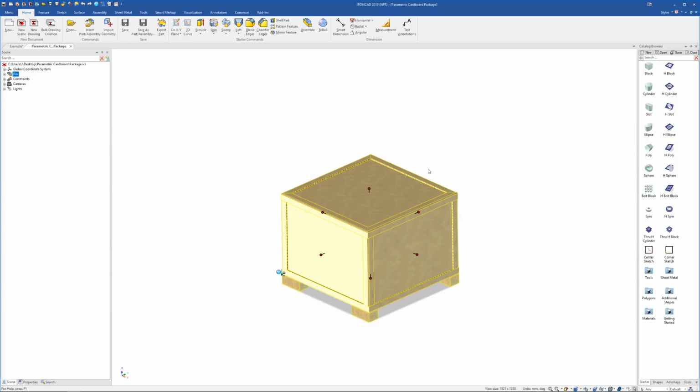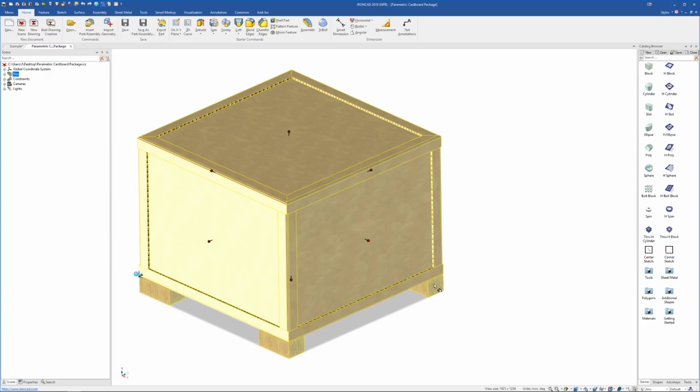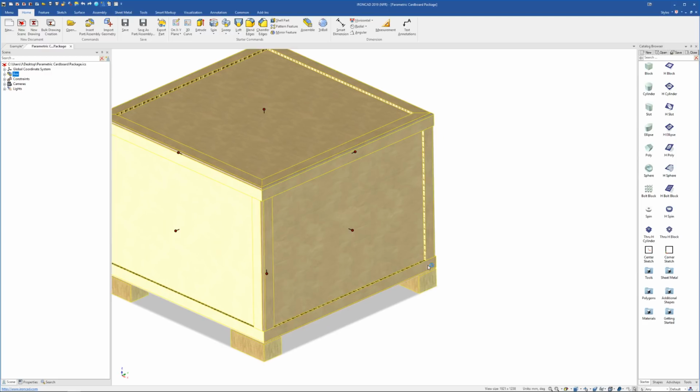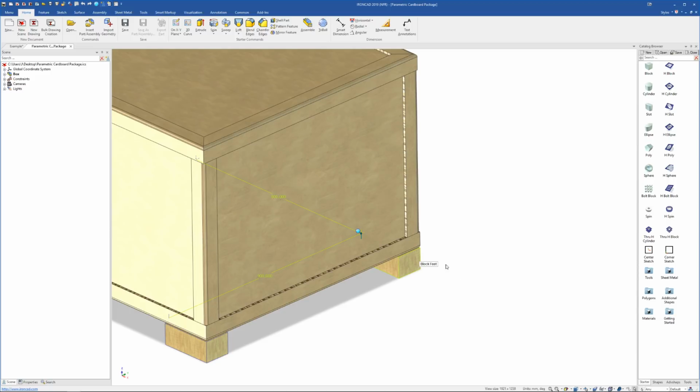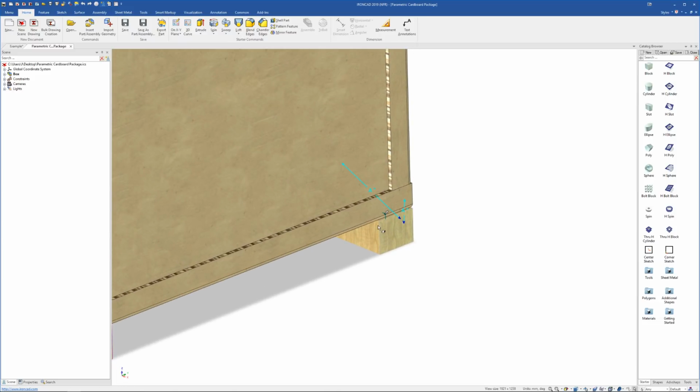And to click down to a shape, obviously with every assembly you create, it creates another click. So if you've got 5 assemblies here, to click down to the IntelliShape is going to be one click for the assembly, in this case, another click for the pattern, another click for the part. And then if you add more assemblies, that click count goes up and up and up and up. Whereas most times, whenever you want to make any actual edits, you just want to get down to the IntelliShape level, which is, of course, this level here.